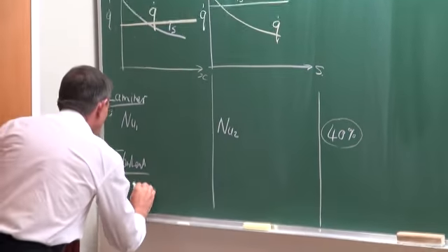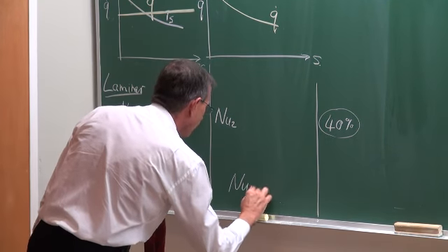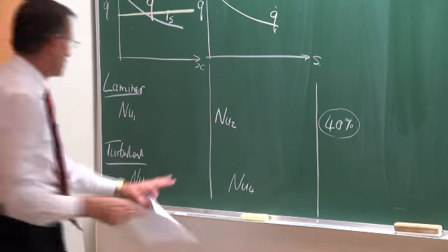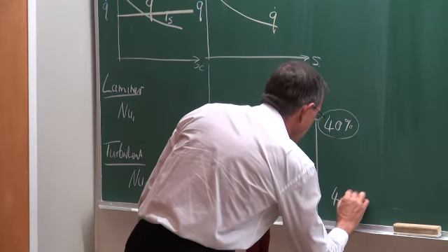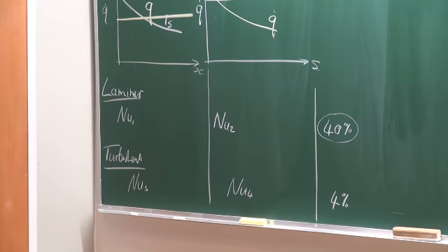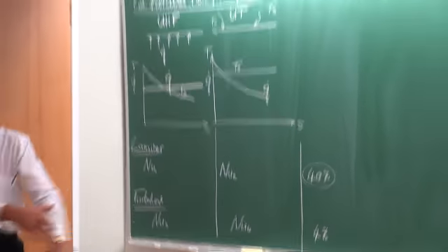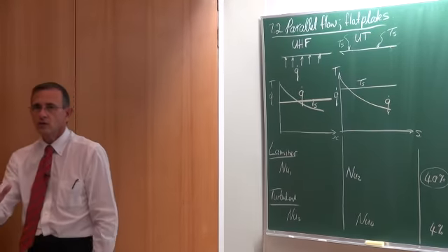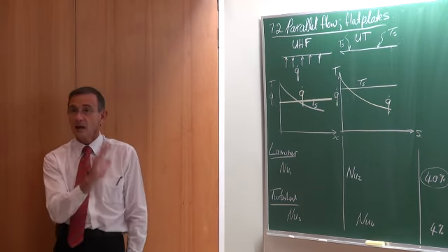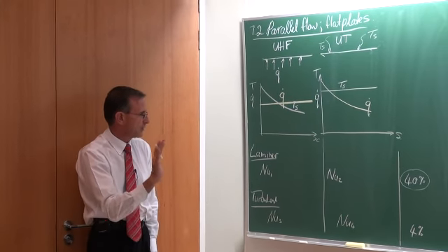In the turbulent flow cases, if we look at the Nusselt numbers, let's call them 3 and 4, there might be many correlations that you can use. If you compare them, the differences would be about 4% and even less. Now in between we obviously also have the transition flow regime. Not a lot of work has been done in that regard, and not a lot has been documented in your textbook. Some has been documented by Çengel and Ghajar, but we are not going to focus on that.